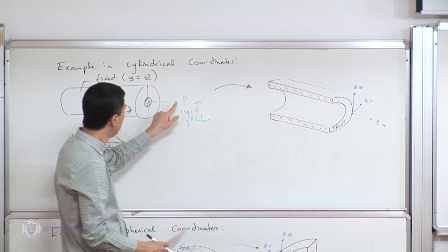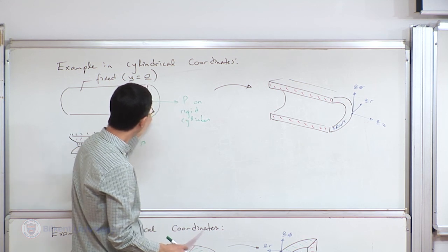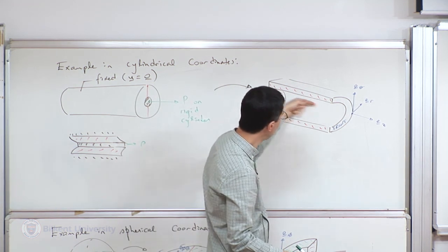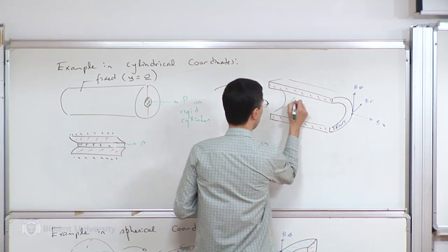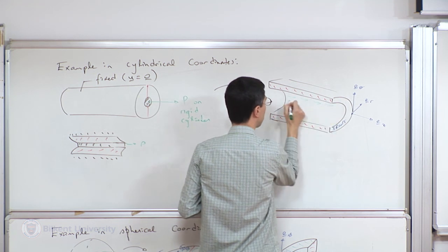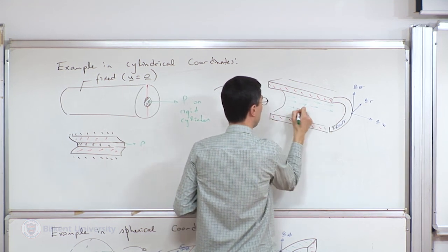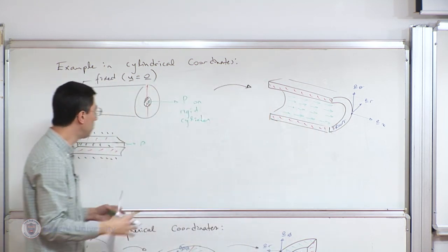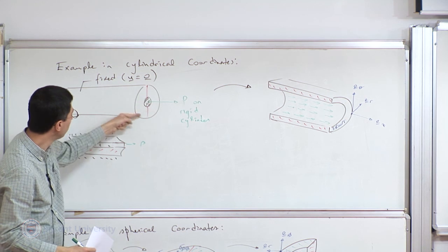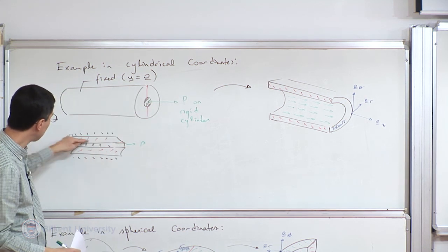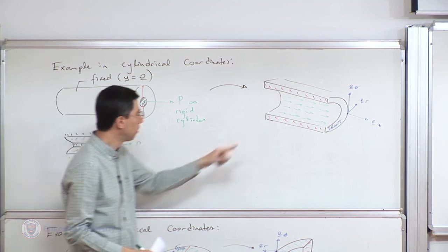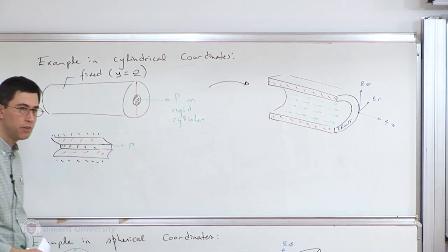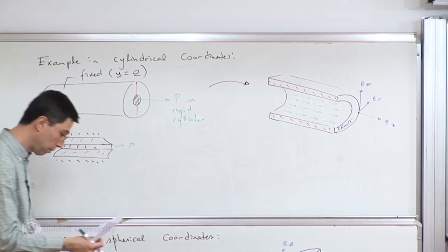Or this force, instead of being a point force on the rigid cylinder on the inside, is going to be distributed onto the inner surface. Perhaps something like this. Yes, you are applying the load at a point on the lead, but the lead is in contact with the deformable outer wooden layer along that surface. And along that surface, therefore, there has to be a distribution of stresses that are eventually equivalent to the force that I'm applying.